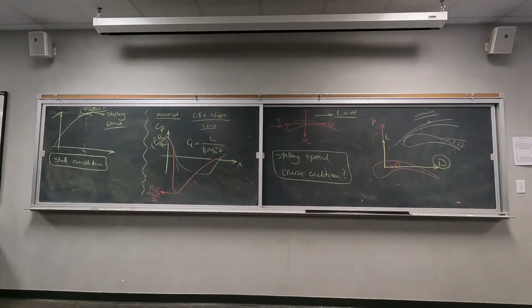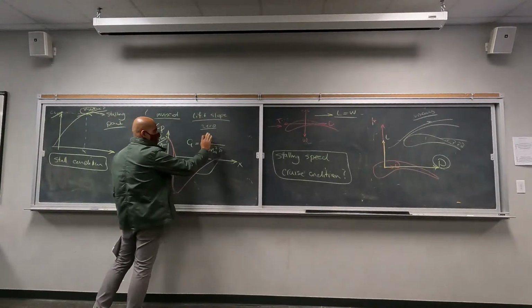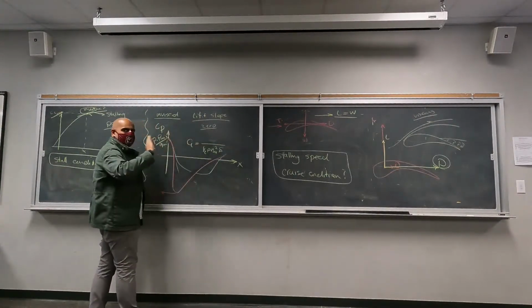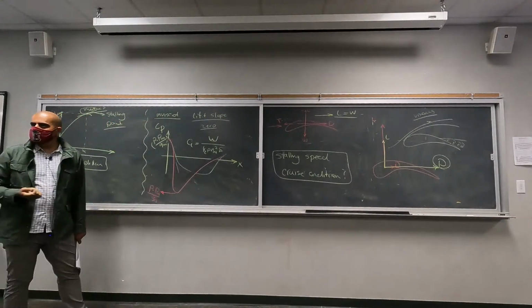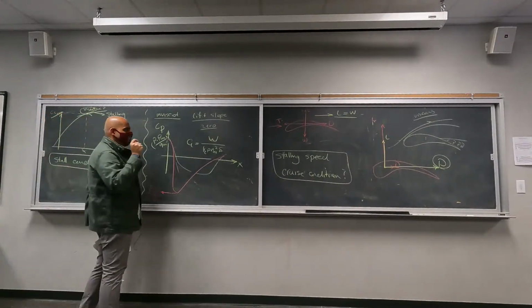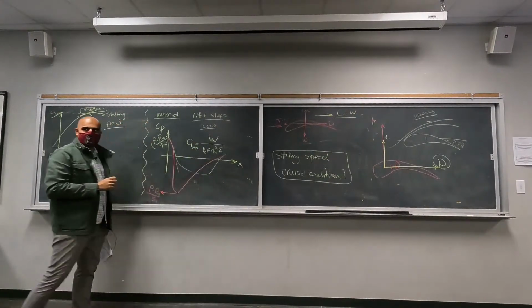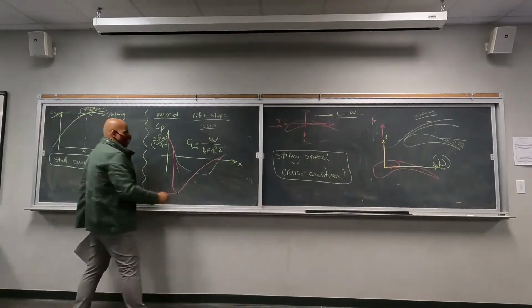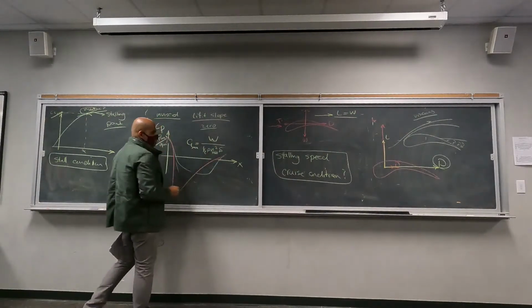Okay. What will happen to this equation during a stall? A cruise condition, in general, doesn't have anything to do with the stall. Your lift will equal weight, right? That's the idea, to maintain the cruise condition. But during the stall specifically, you are going to experience your maximum lift coefficient, right? And your velocity is going to become the stalling speed.